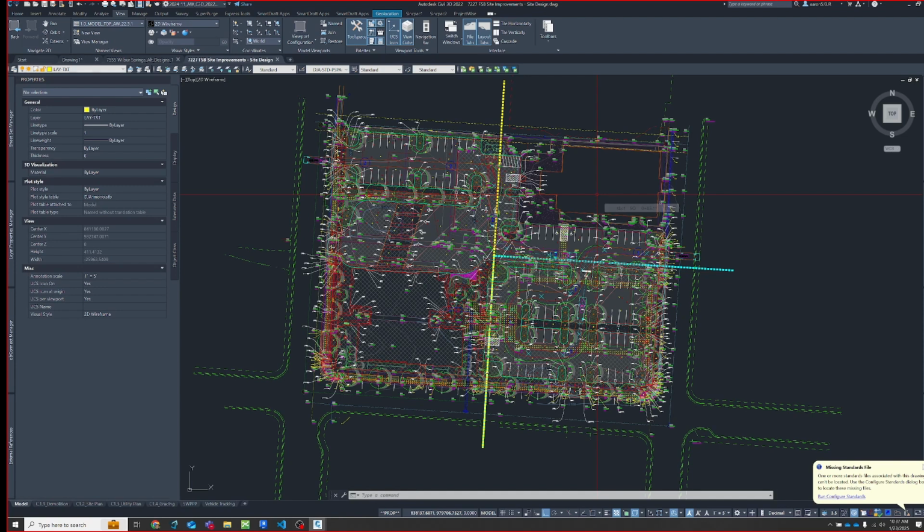Managing your layers is a big part of your skill set to increase your efficiency, to give different design scenarios and phases, maybe go to an analysis view and then go back to your final plot view quickly without missing things, and then you plot it to a PDF and there's five things on that you didn't want. It just helps with all that stuff. So in these couple examples, I'm trying to show the power of layer states and view states for, say, things like different design alternatives.